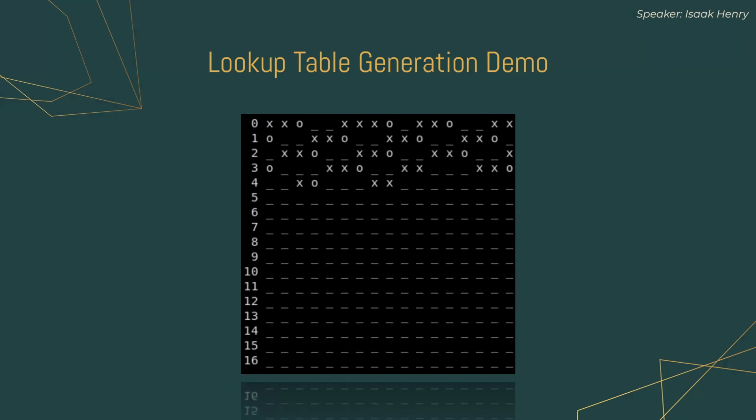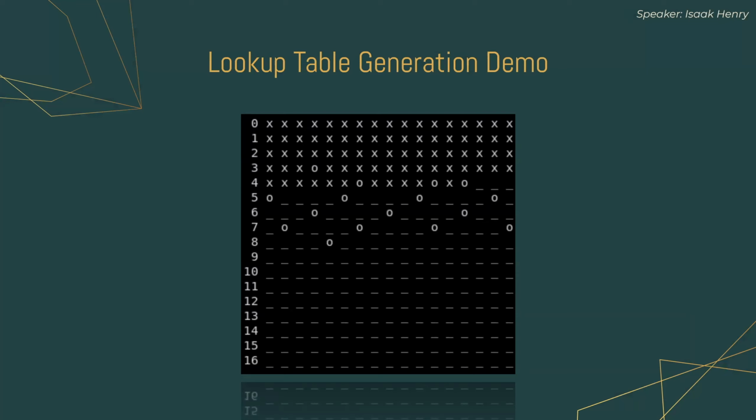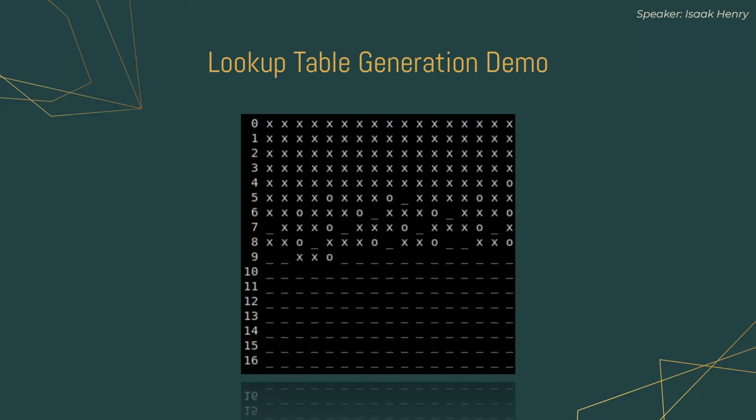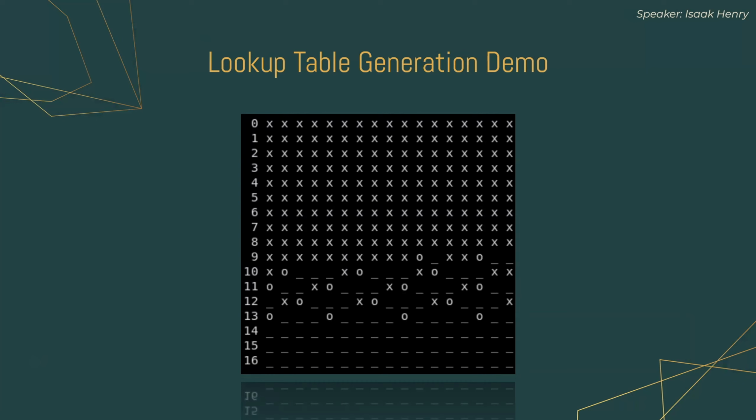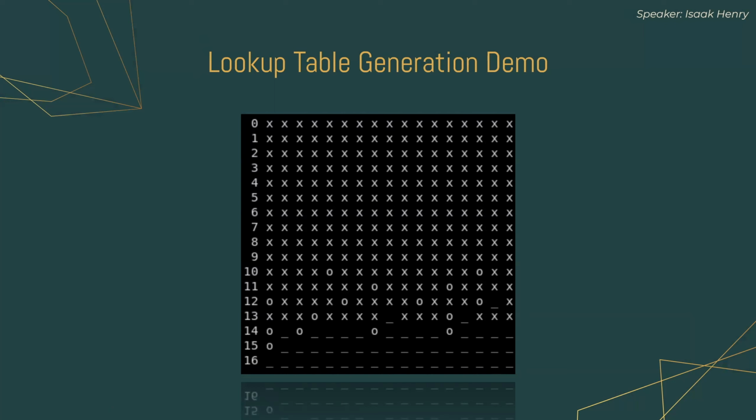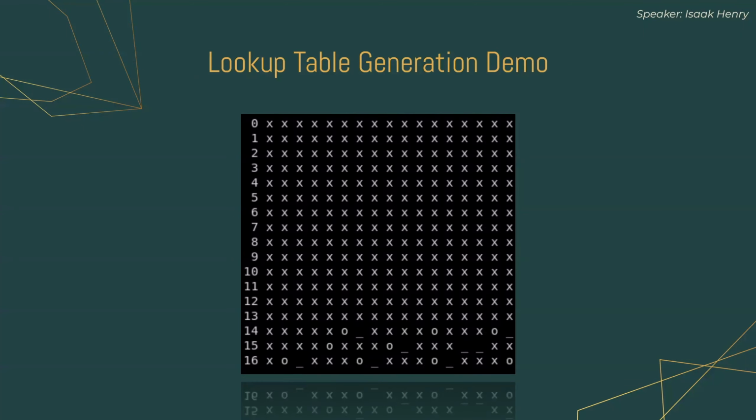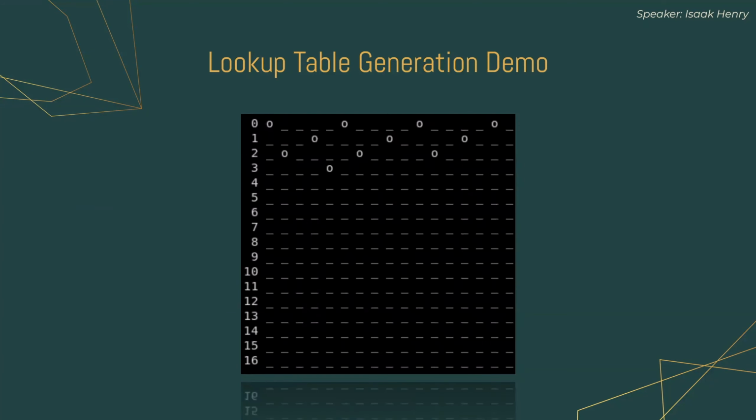Here we have a live demo of a miniaturized version of our lookup table generation. This lookup table takes in the velocity and steering angle in order to find the requested throttle percentage to push to each wheel. In order to speed up the process of the calculations, we use multi-threading, which is visually represented here by the circles. Each circle is a calculation that's currently being worked on, and once the calculation finishes, the index in the array gets shifted to an X.